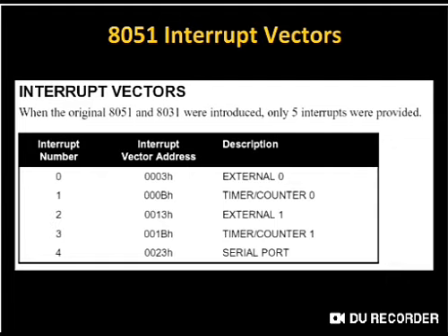Now you may ask, if the program length is too long, for example, if you are writing an interrupt service routine for external interrupt 0, then 0003H is the starting location, but the code may go to say 100 lines. I need 100 locations. So where do you write the interrupt service routine? If you start writing from 0003H, it will overlap with 000BH and 0013H onwards. That's why from 0003H you can have an LJMP instruction and safely redirect the program to a safe location.